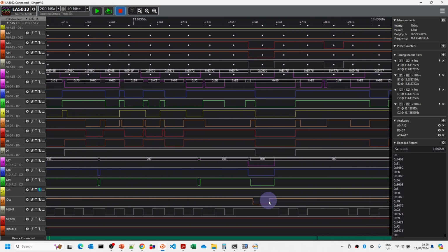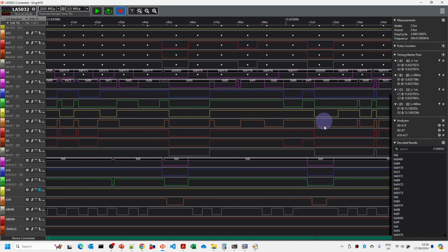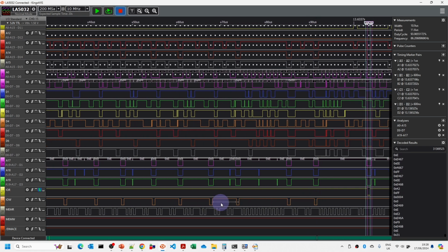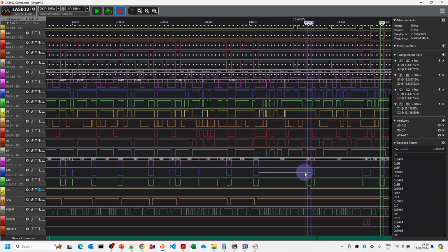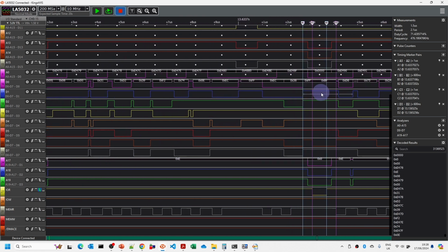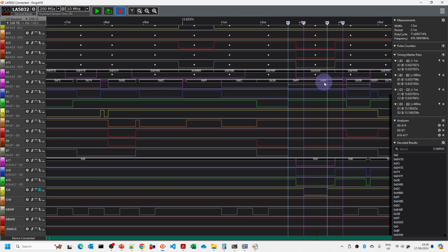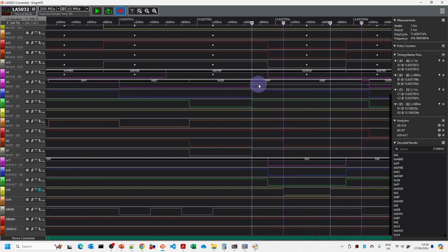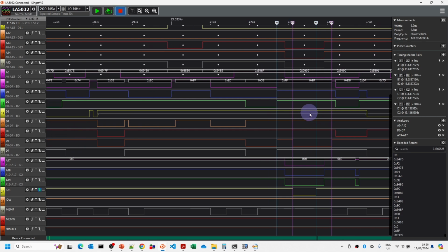Then, in fact, they've been written as 0 and 0. So as part of this test, we set all the registers to FF, then to 0, and now it's reading back 0, and rather than coming out as 0, it's coming back as BF. So something's definitely not right here, and in fact we can see there's a bit of time here where something's not quite right.